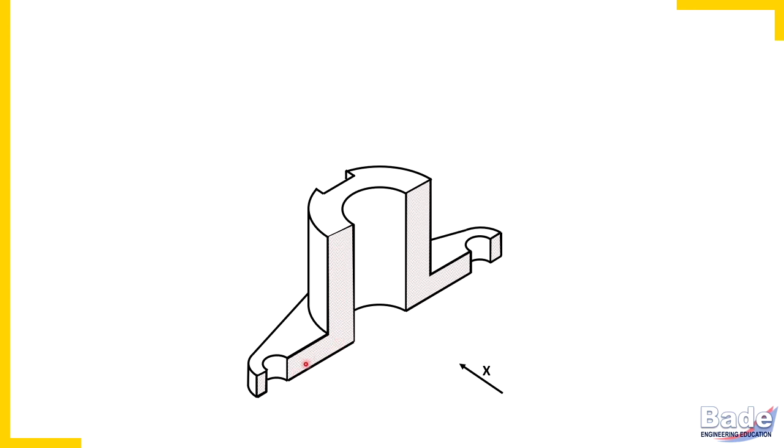You will understand. So this is the newly generated surface, that is the section. But watch here, inside the hole, this semi-cylindrical surface is the original surface. It is not the surface that is created by the cutting. But this colored surface in the drawing now on your screen is a fresh surface that got created because of the cutting. Now try to understand. The portion nearer to the observer is to be imagined removed.